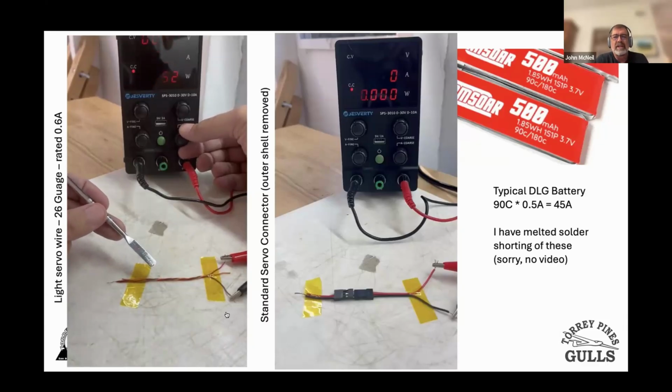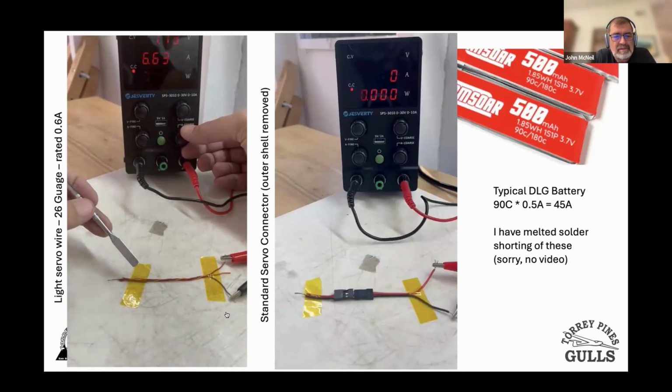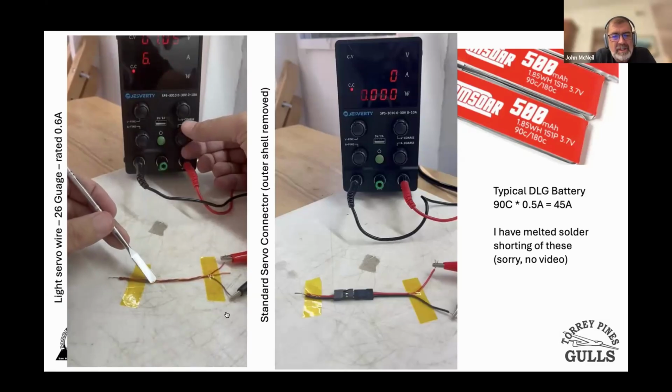Okay, so I'm at 4 amps now, and it's kind of not interesting, but I stopped touching it because I can feel it getting a little warm. Pay attention to the left where it's twisted. So it's almost 7 amps now. Are you guys seeing smoke? So it gets hot first at that magic twisted connection. Now I'm starting to smell it.